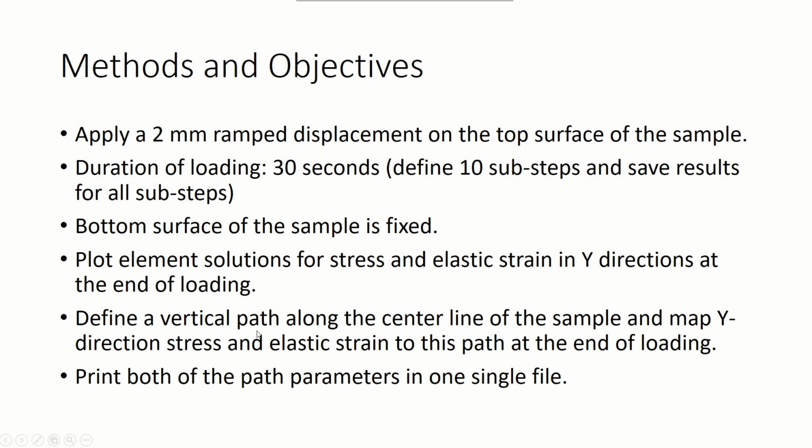And then we want to define a vertical path at the center line of the sample and map the y direction stress and elastic strain and see their changes. And we also want to plot or print those path items.